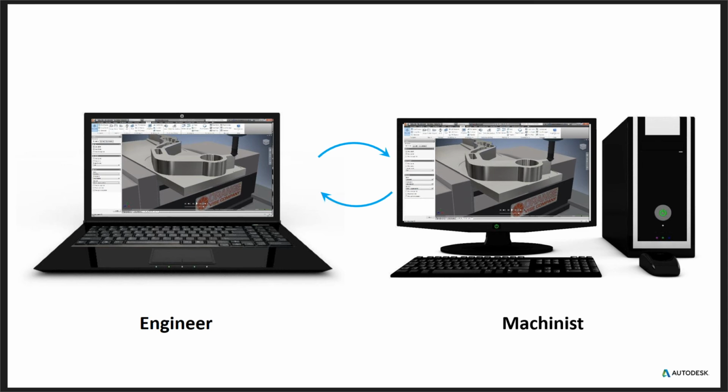If they do make, like Alex mentioned, a change in the geometry, it's not too drastic, right? You just change the size of a fillet perhaps, or you change the length of a line. A lot of that does carry straight over into the CAM environment. You don't really have to change anything. You just have to update the toolpath. Obviously, if you make a huge geometry edit, like you get rid of an entire section of your part, the toolpath might not regenerate properly or as intended. But it really depends on what you're changing, right, Alex?